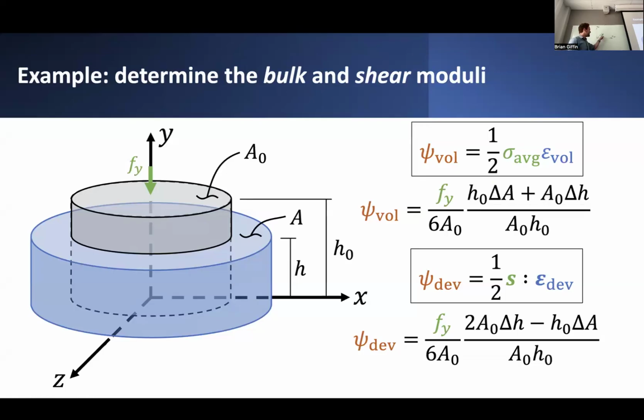So for bulk modulus, basically, if we take some reference point where we initialize volumetric strain and say it's 0, and same thing, initialize average stress and say it's 0 at this point, and then take some other point at which we've increased the load, we can basically define this straight line. We can determine the slope of that line. And then all we have to do to determine this stiffness coefficient is take the change in the stress divided by the change in strain on this two-dimensional plot.